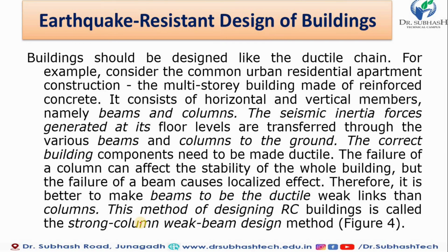made of reinforced concrete. It consists of horizontal and vertical members, namely the beam and column, that should be constructed. The seismic inertia force, which we will see in our lecture 2, is generated at the floor level and transferred through the various beams and columns to the ground. That should be our load hierarchy system. So the correct building components need to be made ductile.